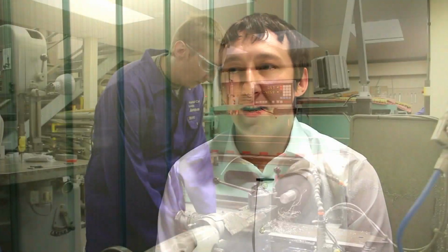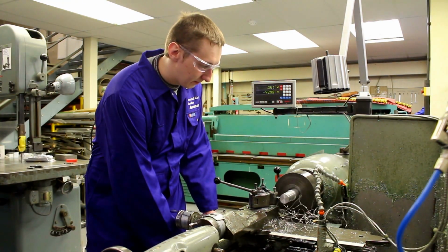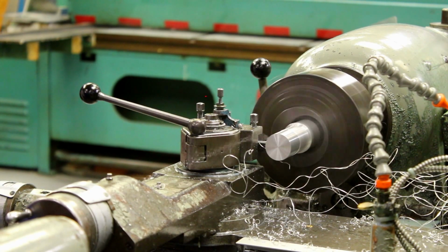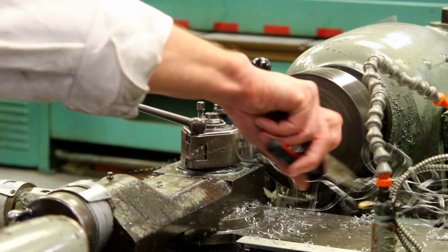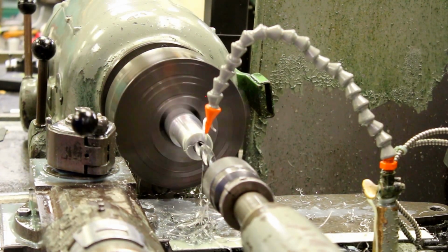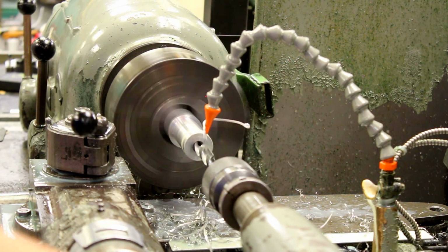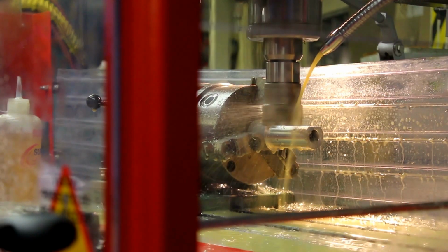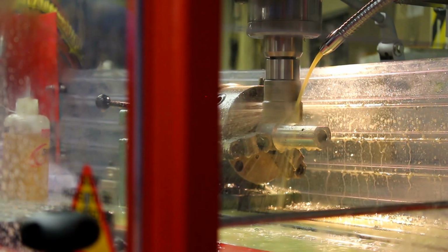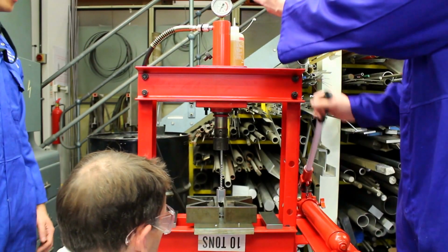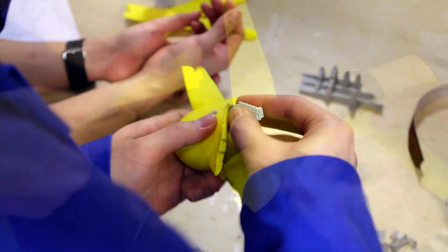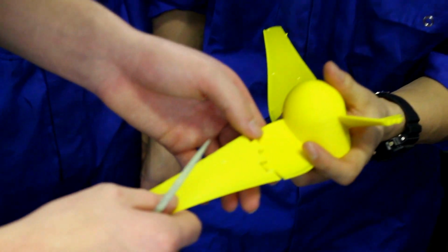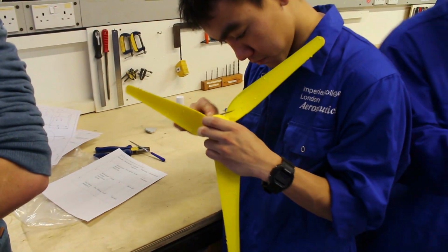We had to manufacture the aluminium hub by ourselves, and we started with an aluminium cylinder. Using the lathe, we reduced the diameter to 30mm by straight turning. We then drilled a hole along the axis of rotation where the shaft would be inserted. Using the CNC machine, we created the three flat surfaces of the hub. The hub was ready after the keyway was cut using a broach. The blades and nose cone were manufactured using rapid prototyping into two parts, which were later glued and sanded to smoothen the surface and remove excess glue.